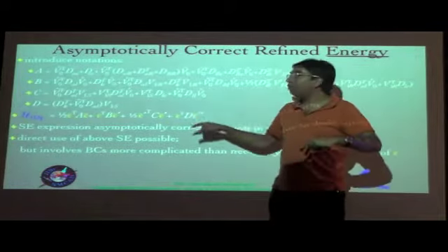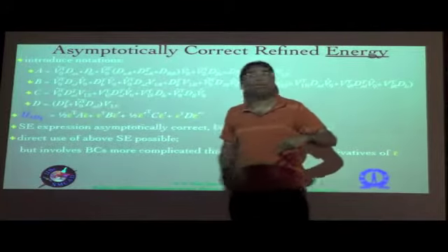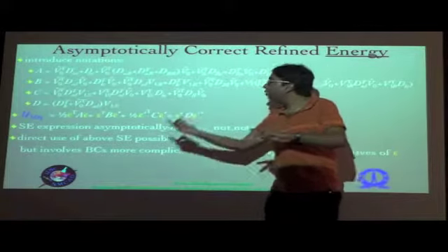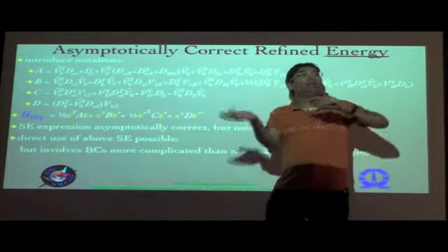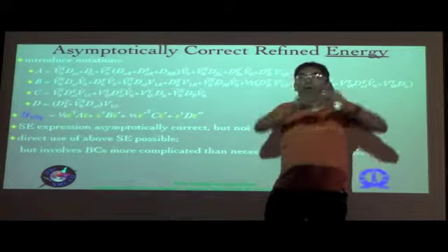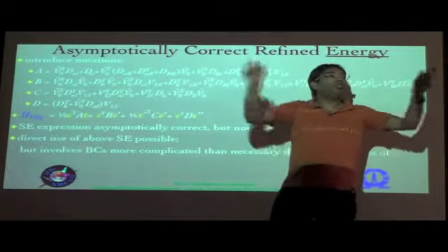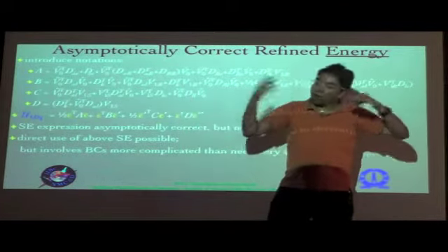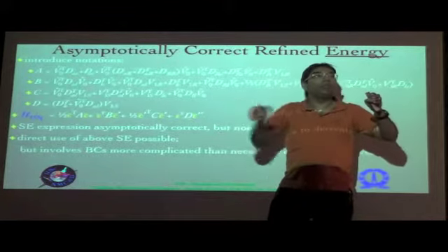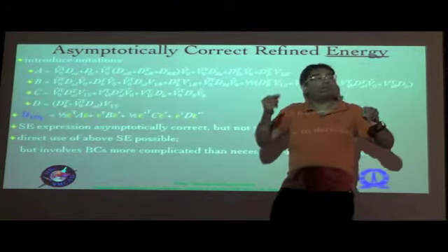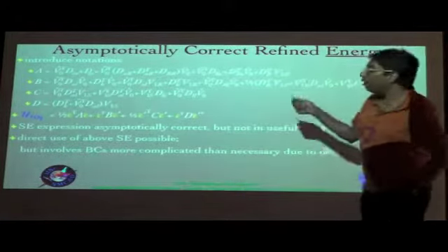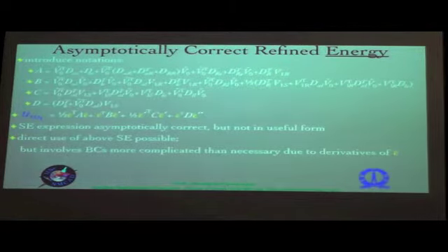And there, if we have these kinds of terms, or even these kinds of terms for that matter, you will have additional boundary conditions resulting, because you would have to transfer these derivatives on, and when you do that, you have to use integration by parts along the length, and eventually you end up with some more boundary conditions associated with the ends, or the existing boundary conditions will have additional terms which are more difficult to deal with and not physically intuitive to you. Not that it is impossible to deal with, but it's more complicated than usual. That is one of the disadvantages of this.